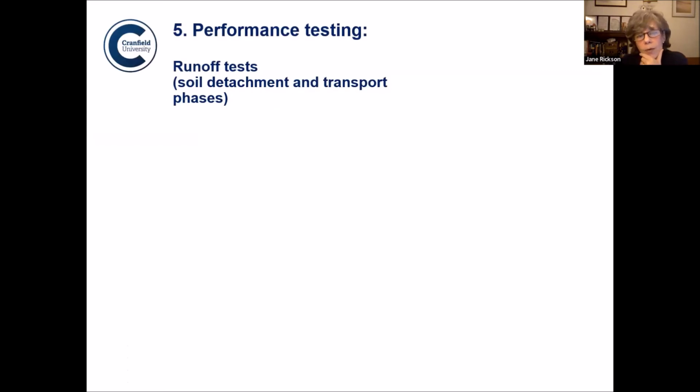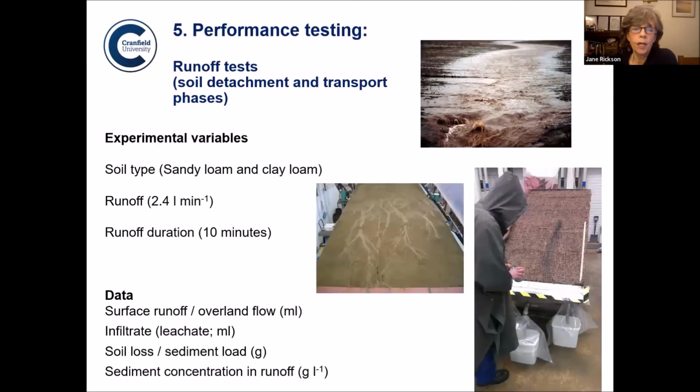So we thought, okay, that's rain splash. Let's now have a look at runoff and how these different products perform where we've actually got surface overland flow, which is much more realistic to field conditions. So again, we had our rainfall simulator applied onto our large erosion rigs, our runoff rigs, that can be tilted at different gradients. The rainfall is then applied. You can just see this black mark here. This is our tracer where we were measuring the velocity of flow. In this case, I think it's a jute product that we then installed on the soil surface.